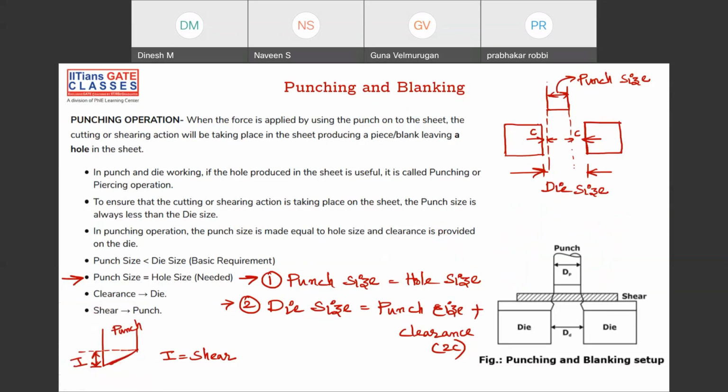You have to provide that shear, and that shear is given on the left hand side of the page. This is what is your shear. Okay. And now this shear is provided to the punch. In the sense, your punch is not like this, your punch is something like this. And this is what is your shear height, the distance.